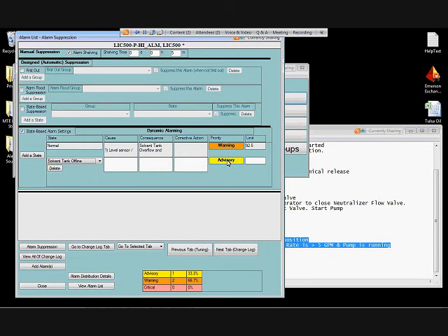It's actually pretty important because I know when the tank is offline, it should actually be empty. So we're going to set this alarm to have a different alarm limit when the tank is offline, something low like 5 feet, which will let us know if for some reason the tank is starting to fill when we believe that it should be offline, which would mean we've lost isolation to the process.